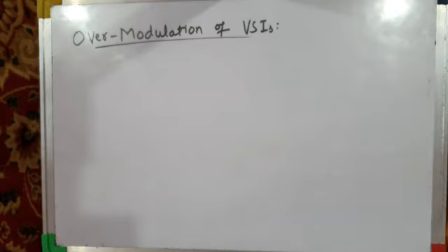If your load is an induction motor, then the winding reactance itself is sufficient to filter out harmonics in the current because of this PWM operation, and thus produces almost purely sinusoidal winding currents in the induction motor, right?